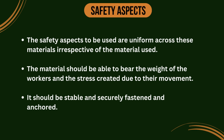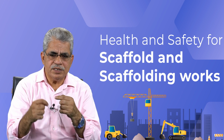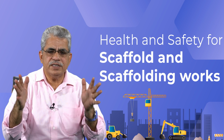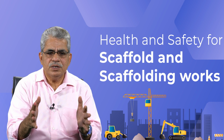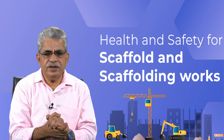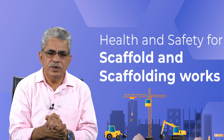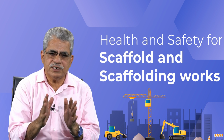We should fasten and anchor the scaffolding and also the members of the scaffolding, because if there are chances of any movement in the different members of the scaffold, or the whole scaffold can move or sway, then this will not provide us a safe work environment. So we have to take care of such situations.